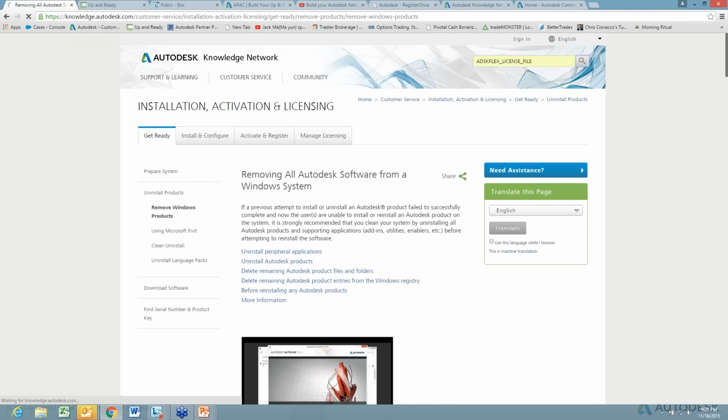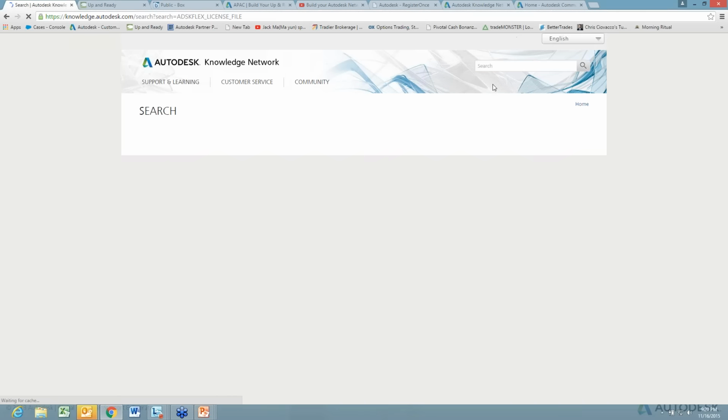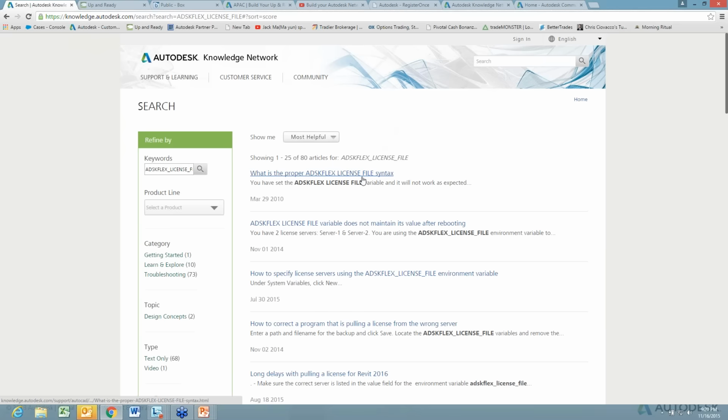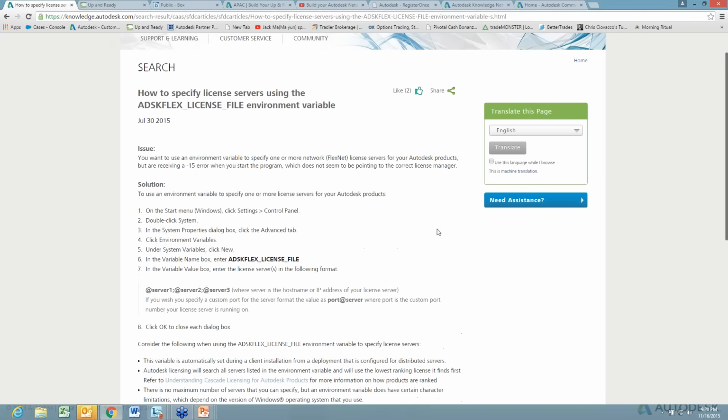All right, so if you have no network connectivity, how will you get the Revit content library? Well, yes, that is one of the unusual products to get installed. The Revit installer installs the Revit content libraries, but they are not included in the Revit download. So during the install process, it has to go and download the Revit content from the Autodesk server. We actually do have the Revit content up on, I believe, Dropbox.